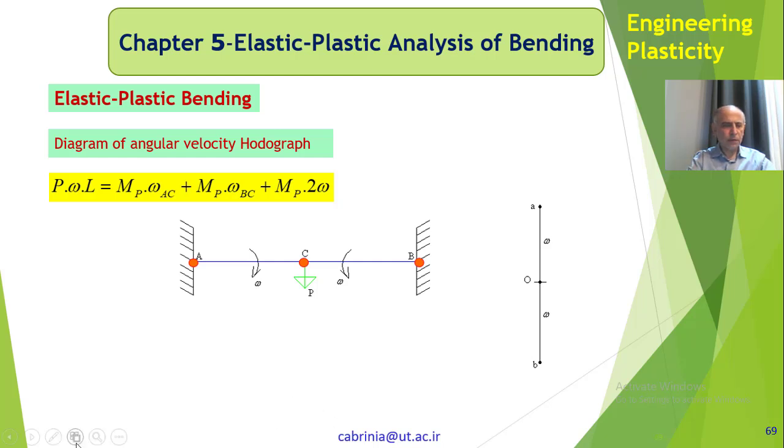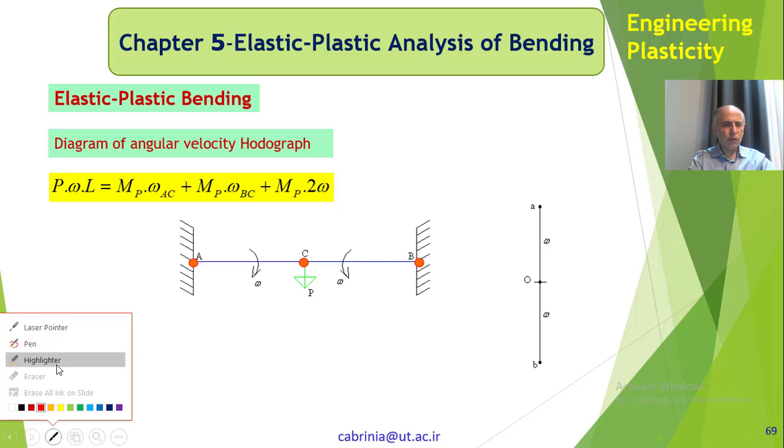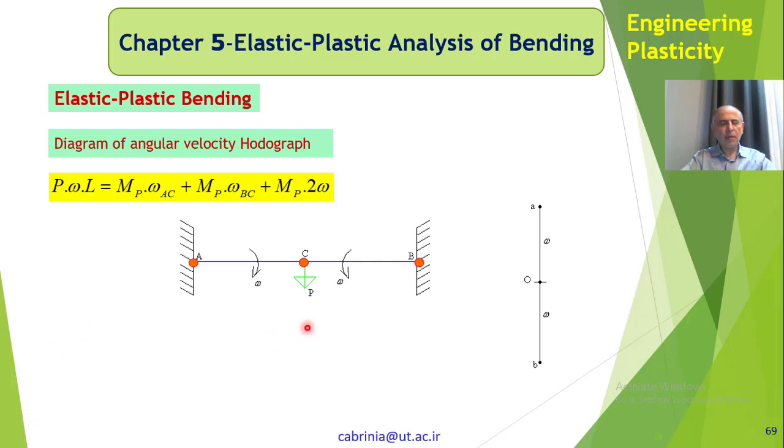In this figure I have shown you the same problem that I solved at the beginning of the introduction of the virtual work, and that is a built-in beam, AB. At point C in the middle, the load P is applied, and we assume that A, B, and C become fully plastic when P reaches the collapse load and the beam collapses.